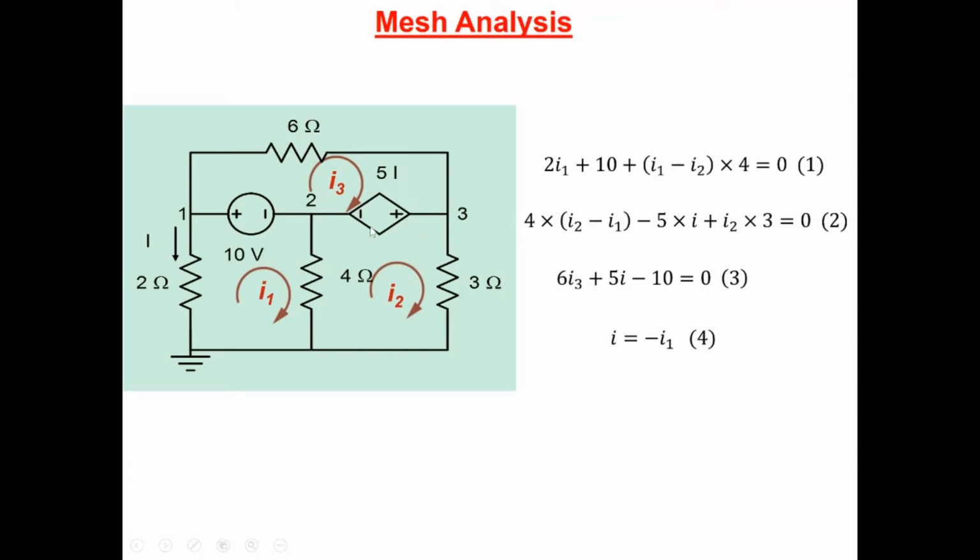And now what we have done is we have taken the circuit and transformed it into a set of equations. Now it's a set of linear equations which we can solve to get these currents. So if my analysis is correct, then I1 is minus 1.5, I2 is 0.217, I3 is 0.4 amperes here. And so you obtain all the mesh currents, and through the mesh currents, of course, you can get any of these currents. For example, current flowing in the 2 ohm resistor is simply equal to I1. Current flowing in the 6 ohm resistor is simply I3. Current flowing in the 3 ohm resistor is simply I2.